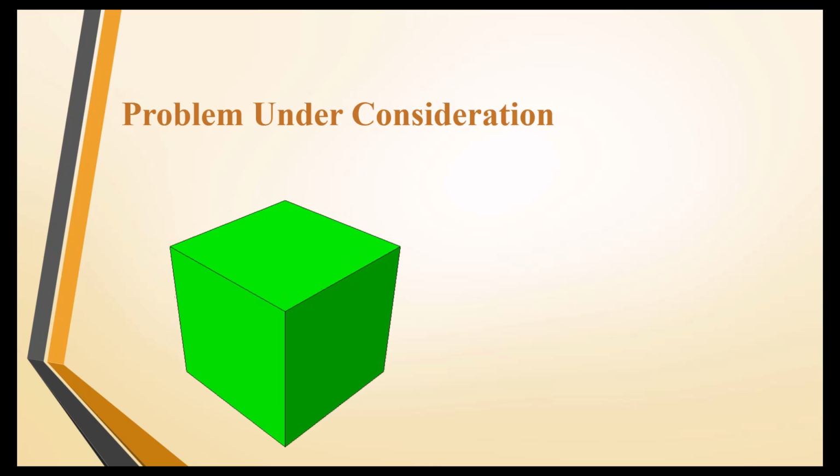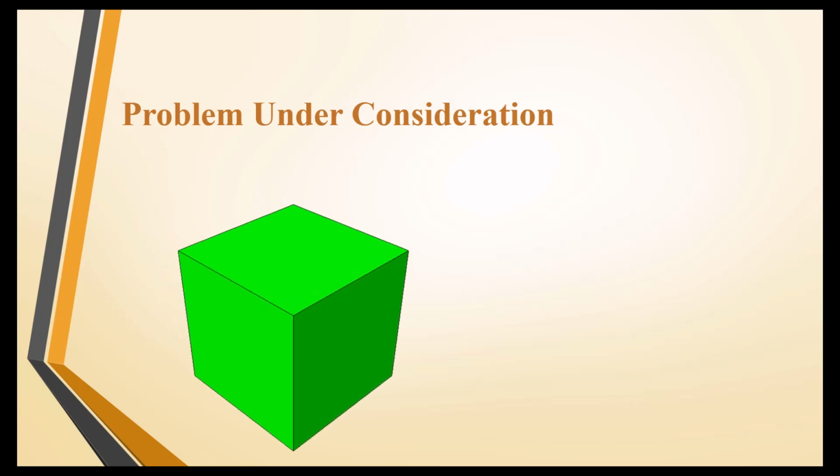The boundary conditions are defined as follows. The back face of the cube is fully fixed, while the opposite face is displaced by 2 meters in the x direction. The objective is to analyze the stress-strain curve associated with the element of interest. To solve the problem, the general static step in Abaqus is employed. We will now enter the Abaqus environment and proceed with the modeling process step by step.